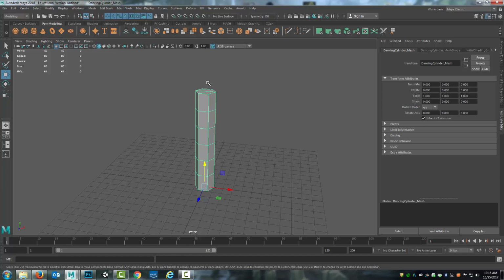However, when you get into rigging and animation, it relies on the history to be able to make things happen. And so there's a difference between mesh history, things that you're trying to build, that's non-deformer history, and history that's being used for rigging and animation, which is deformer history.